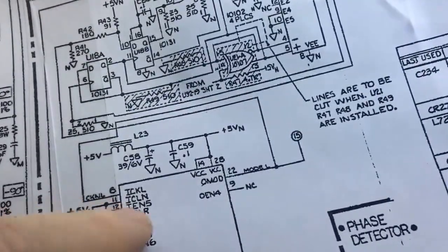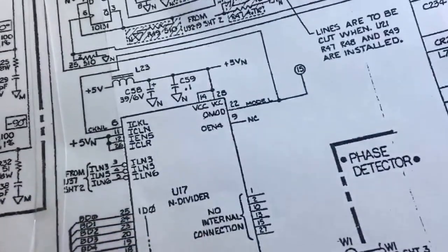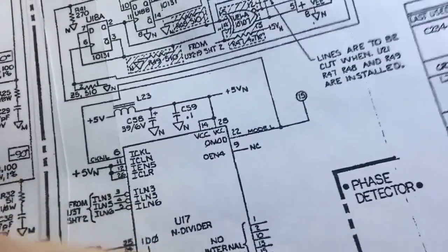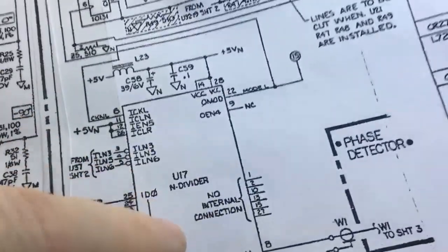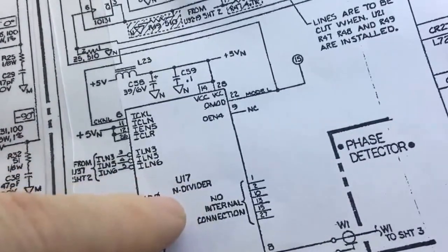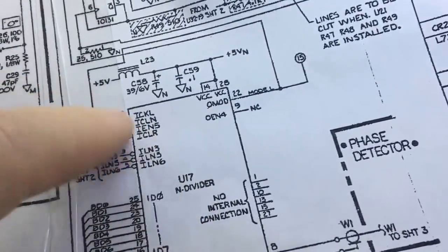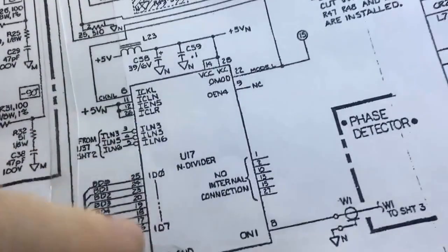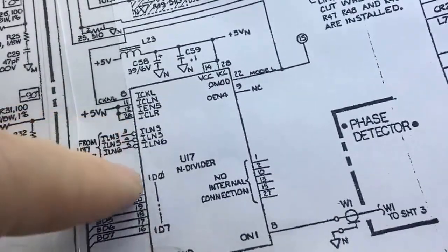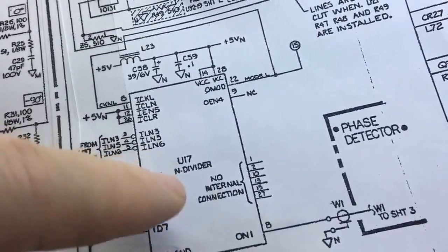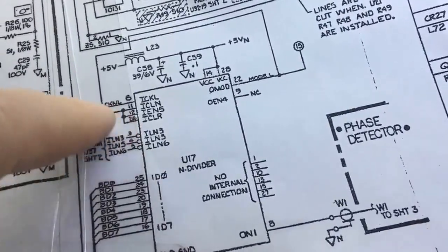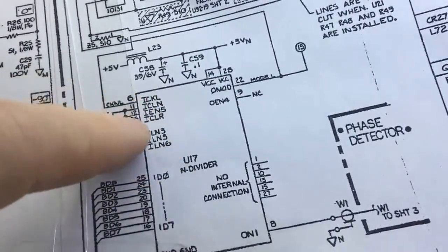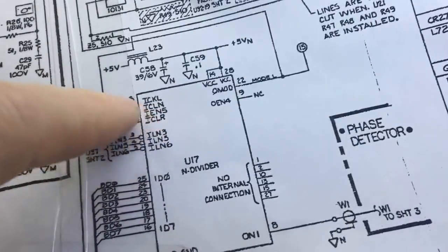So if that's got to take 21 megahertz in and divide that down to 1 megahertz, that's divided by 21, isn't it? So I was actually thinking as well, if this chip has failed, and I can determine what frequency comes in and what frequency's got to come out, and that's the digital input there, I could probably write something for an Arduino, maybe, depends on the frequency steps. I might be able to write a little microcontroller program with the Arduino.